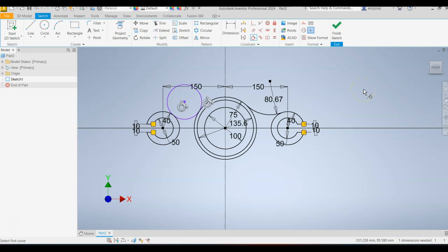Okay. Let me refer back to the drawing. The drawing's missing this dimension. I assume that would explode out. It used to do that. It used to just get real big. But anyways, tap escape a few times. This radius, I need to make the assumption that it's 75. So let's make sure that this radius is also 75.